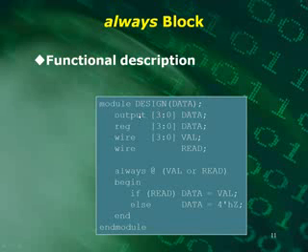And we have an output data, and data right here is a 4-bit wide register. Now, again, I'll just mention, this is compatible with the 1995 version of Verilog. And in the newer 2001, you can put this reg right here after output, so you wouldn't have to have two separate lines.